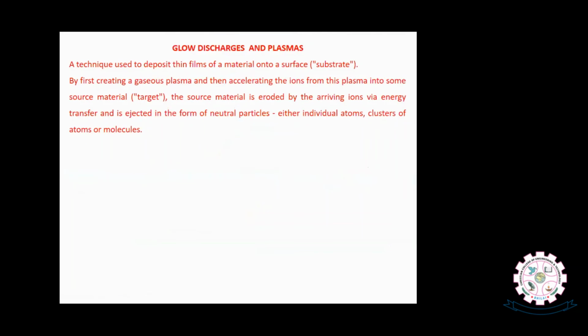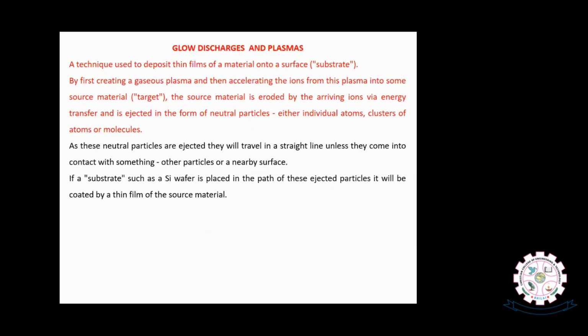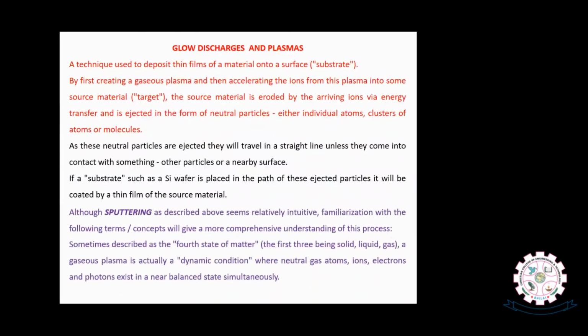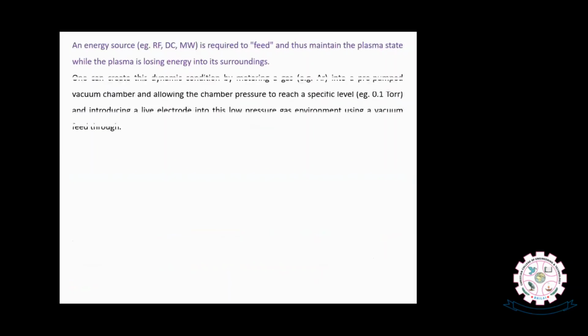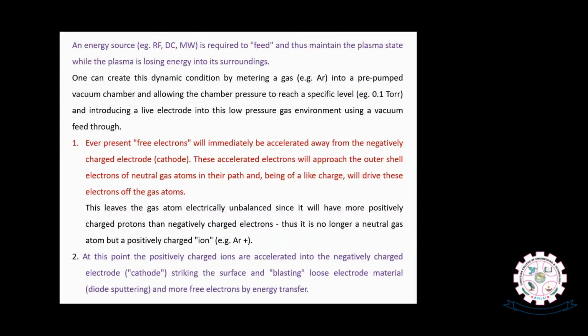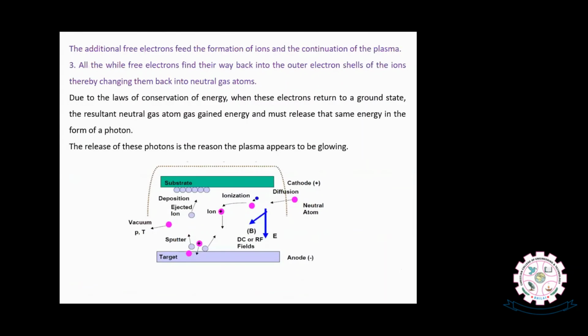The best method, and which is generally used among the scientific community when it comes to PVD, is sputtering. The sputtering technique is a very simple technique. I will explain the sputtering in a few minutes with a video, so that you will be able to understand. So this is the general setup. This is the target. For example, this is your barium titanate target. You want to deposit barium titanate atoms onto the substrate. So this is my substrate, this is my target.